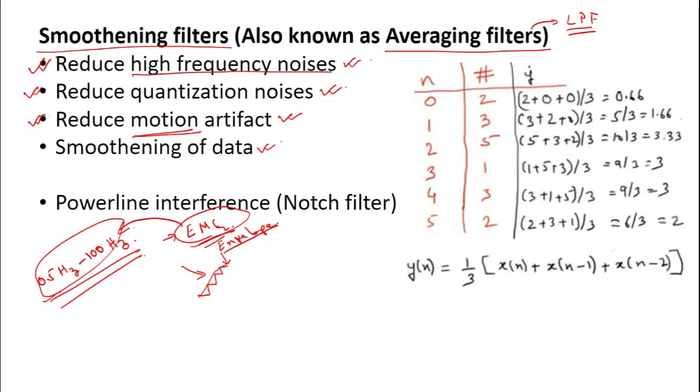So during the breathing, there are every chances that the electrode may move, and due to the movement of the electrode, there would be a change in the impedance levels at the electrode skin interface, and that change in the impedance levels will result in the incorporation of high frequency noise in the ECG signals.